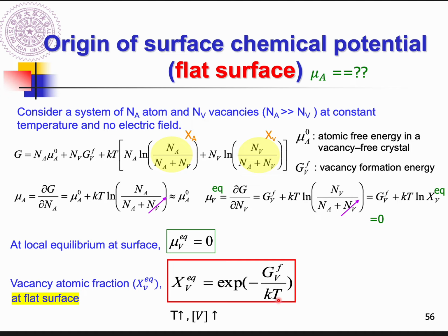Is it the temperature? No. Yes, it is the vacancy formation energy. For sure, the vacancy formation energy on the flat surface is different from that on the curved surface. So we need to modify this term. And how to do that?